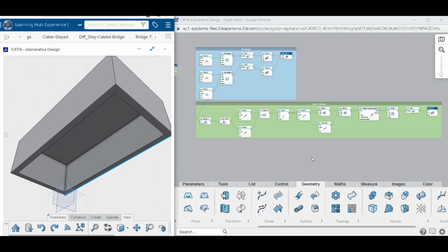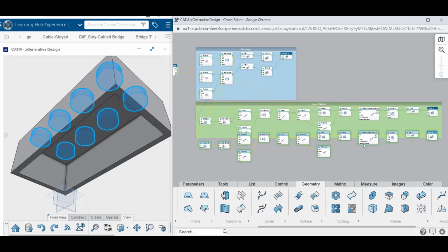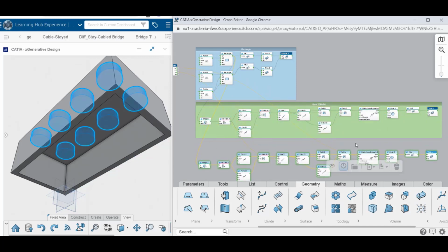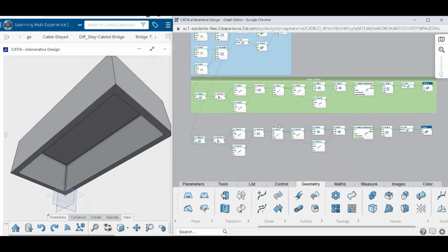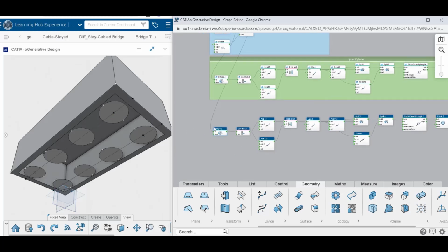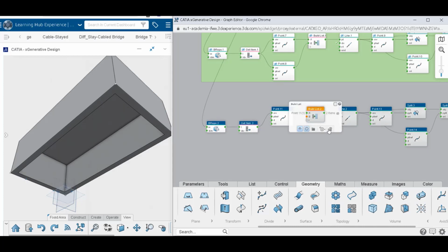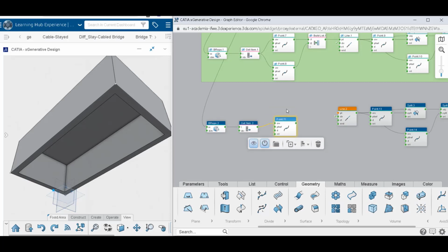So now we'll do the inner cylinder of the piece of Lego. It's pretty close to the previous upper cylinder style, so we will duplicate all the group and put it right at the bottom of it. We'll name it inner. So what are we going to change in this group in order to have our inner cylinder?